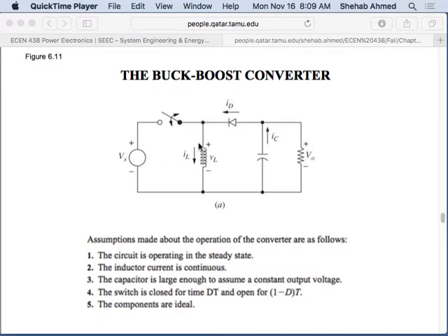And this is what we saw in all the previous converters, and the converters that I skipped in the chapter. They're all the same. They would involve deriving the whole voltage input-output characteristics, then looking at the voltage ratings of the switches, then the average currents of the switches, and then the values of L's and C's. It's a flow. The flow is the same for all the converters.